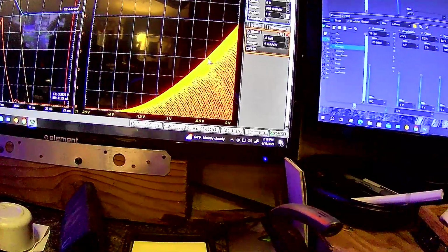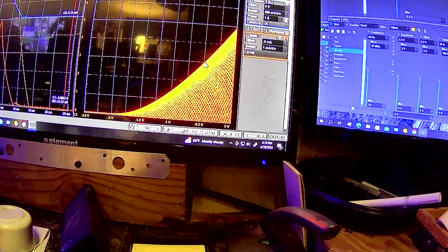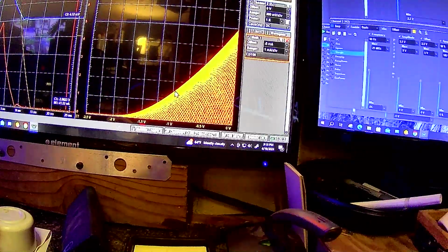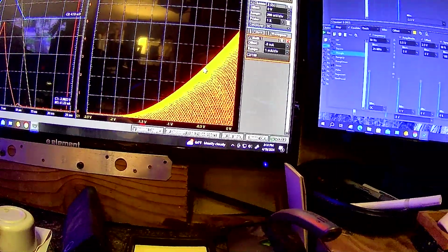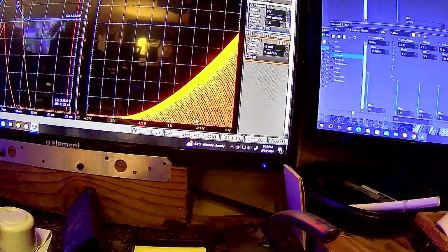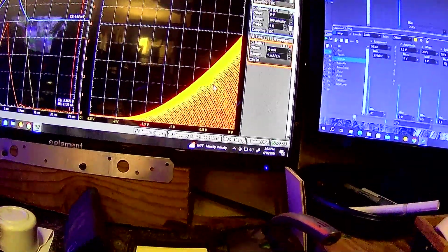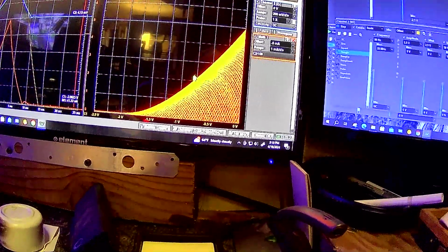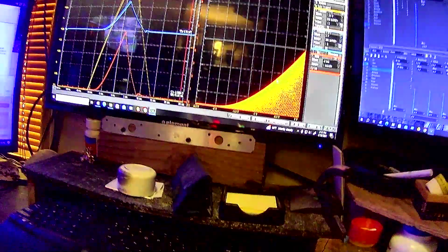For 3 milliamps to 1.5 milliamps change. So that's about 1.5 milliamps for a half a volt change. So that'd be 3 milliamps per volt. In other words, this is approximately 3 millisiemens.